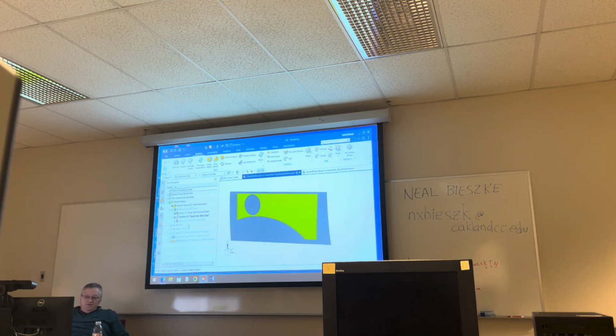So I renamed the feature, but because we're going to involve it with links, the naming of the sheet bodies makes linking a lot easier, or better, because you see the names. So I wait for the three dots, select it, go to the sheet body. This is a new sheet body, it does not yet have a name. It says sheet body of, but it doesn't have a name right after it.